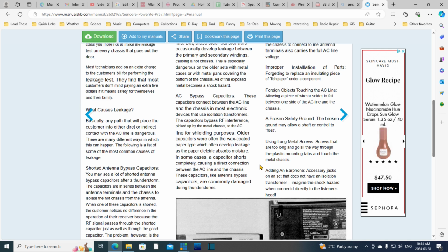Your feet are a meter away from the fence. There's a potential gradient in the ground. The voltage is rolling off as you move away from the base of the fence. So how much voltage would be there? In Canada, touch voltages in those situations are expected to reach 8,000 volts. The theory is they last for such a short period that it would not kill anybody. To make it lower costs a lot more money.